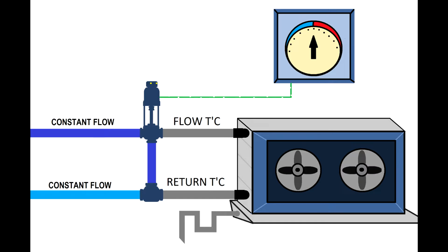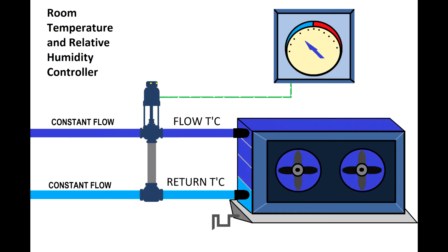So I will explain to you how this system works. To cool the premises, first we have to have a demand, and we have to set the thermostat to demand a lower temperature. Then the thermostat will instruct the actuator to open the valve that allows the cooling agent to pass by to the heat exchanger. The fans will move the air to the very cold heat exchanger, and the air will be cooled.